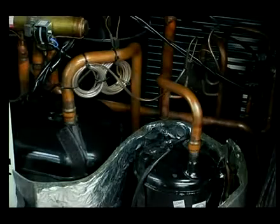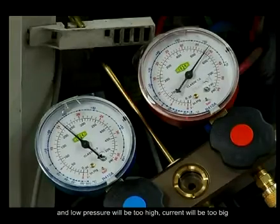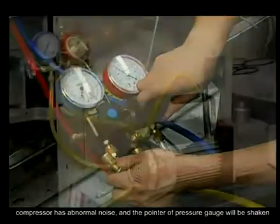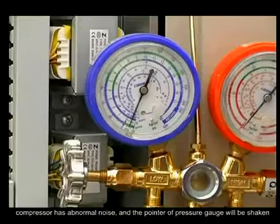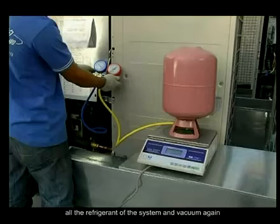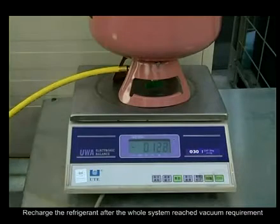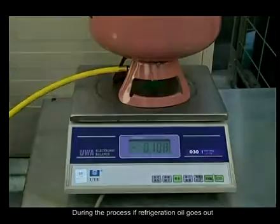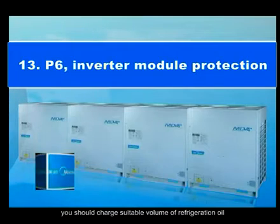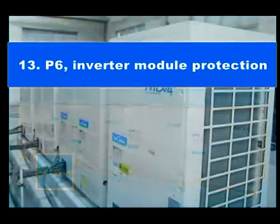If the system is mixed with air or nitrogen, the phenomenon is that high pressure and low pressure will be too high. Current will be too big, the compressor has abnormal noise, and the pointer of the pressure gauge will shake. If there is such a phenomenon, please discharge all the refrigerant of the system and vacuum again. Recharge the refrigerant after the whole system reaches the vacuum requirement. During the process, if refrigeration oil goes out, you should charge a suitable volume of refrigeration oil. P6. Inverter module protection.